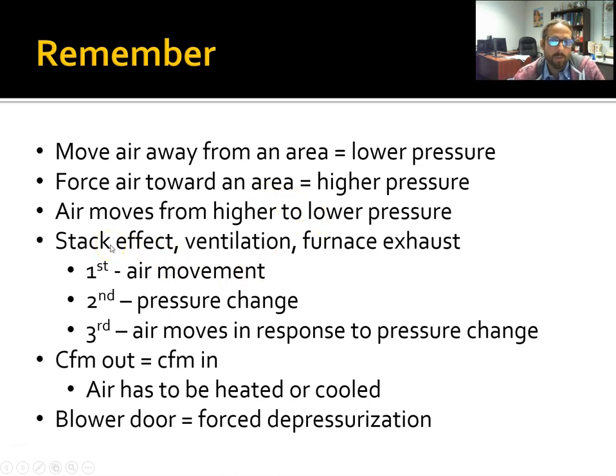Remember, it's kind of like this multi-step process for the stack effect, ventilation, and furnace exhaust. It's all very similar. Number one, you have air movement, right? So with the stack effect, you have air that's moving from the bottom toward the top of the building, okay? And that causes a pressure change. So up high, air is forced into it, so that increases the pressure. Down low, air is being moved away from it, and so that decreases the pressure. And then air comes in to replace that low pressure area, and it's being forced out of the high pressure area. And same thing with ventilation and furnace exhaust, right?